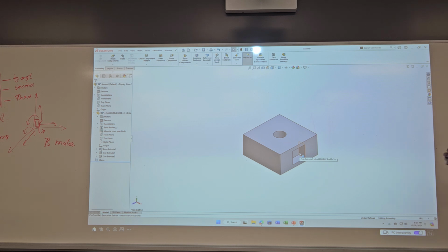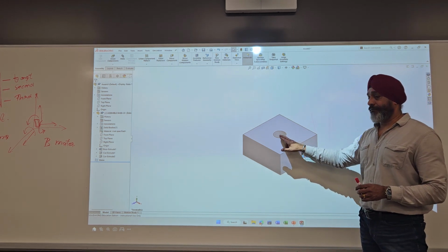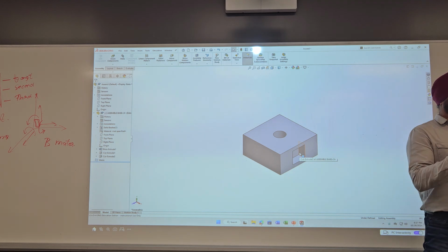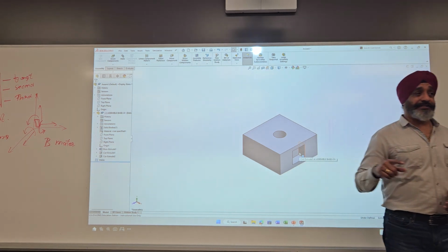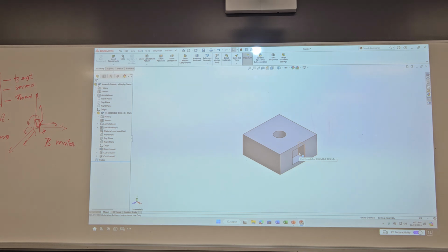And now let's mate it. Last time, with the barrel, we mated it to the different faces. I think when I designed it, I have the origin here, right in the center, as you would do if it's a rectangle or a square part. So one way, which is the faster way to align it to the origin, is to create a mate between the origins.